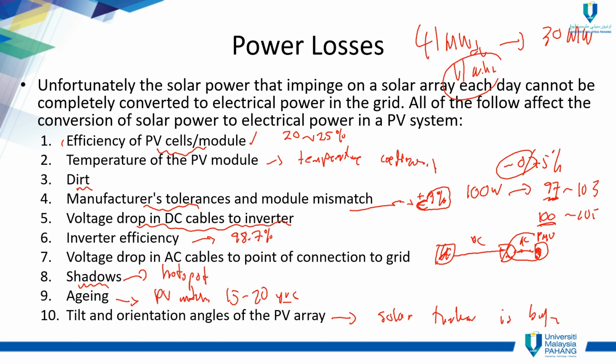Our job is to deliver the power, the inverter. But yes, for the AC, the cable we do have to pay for. Pull the cable from the inverter until the step-up. There's a step-up in the solar farm. They have a transformer stepping up to 11 kV. Then from that 11 kV it travels several kilometers until the substation. So until the breaker side, the cost is also on the developer, the owner.